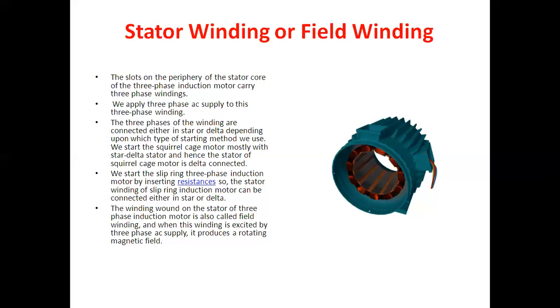The winding wound on the stator of the three-phase induction motor is also called the field winding, and when this winding is excited by a three-phase balanced AC supply, it produces a rotating magnetic field that we have already seen.